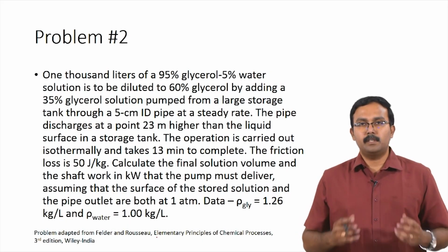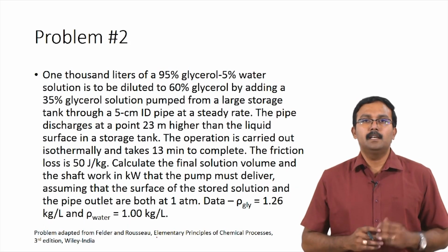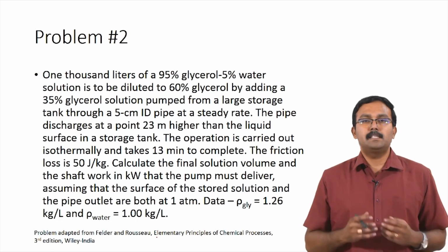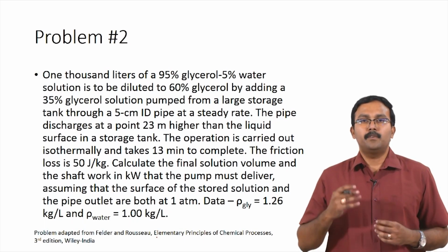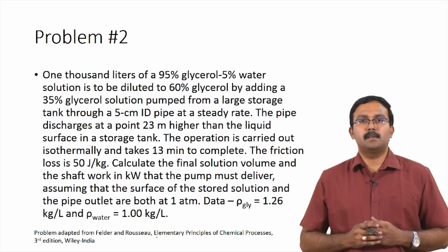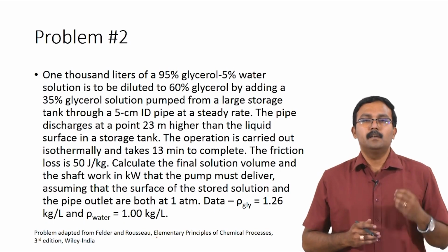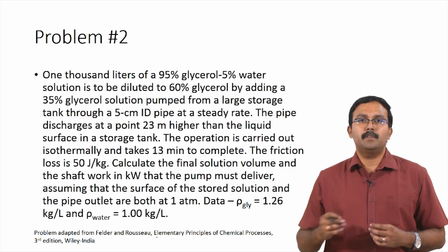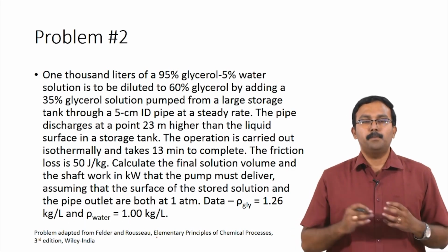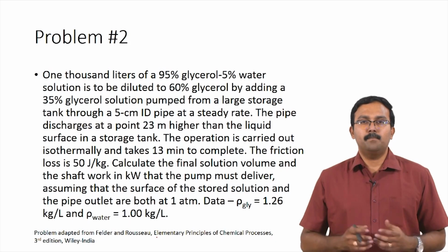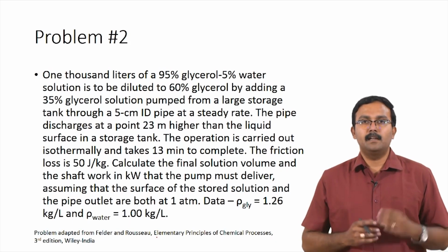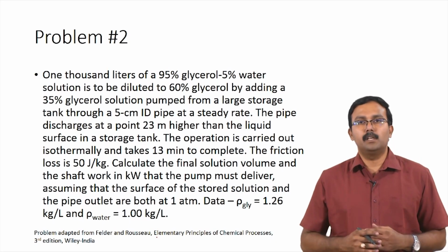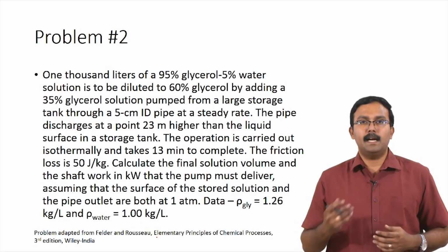So, the first step for this problem would be to calculate the density of the mixture so that we can get the mass of the mixture which is being fed. For this we first need to make a simple assumption. The assumption would be the volume of the mixture would be equal to the summation of the volumes of the pure components. By that what I imply is, when glycerol and water are added, there are no interactions which result in change in volume, or in other words volume is additive.